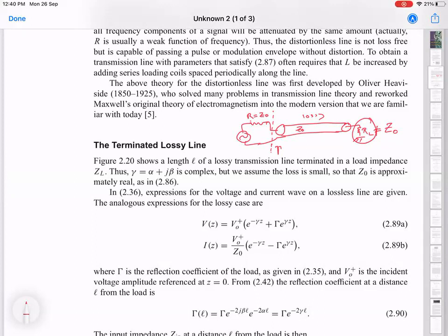But if for some reason you have to connect a transmission line between your device and the instrument, you cannot use a highly lossy transmission line at all. You will completely lose the information of what the reflection coefficient is. So the worst scenario is that if the attenuation is so large that you get nothing back. Right? So that's the way to think about it. The information about the reflection coefficient here will never make it back to your instrument here, so you cannot measure it at this point.